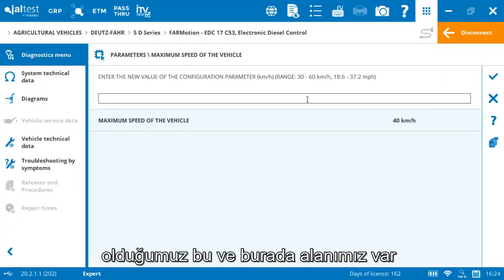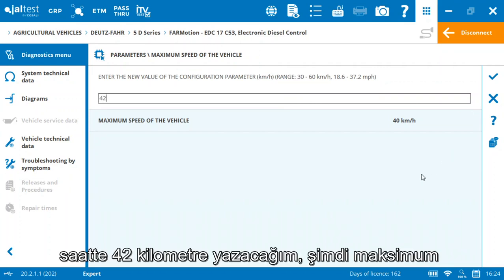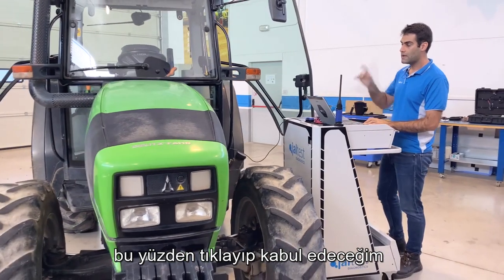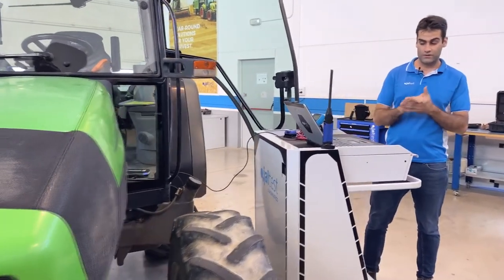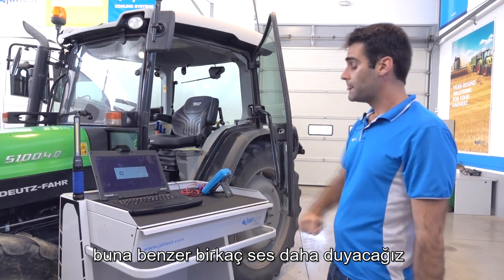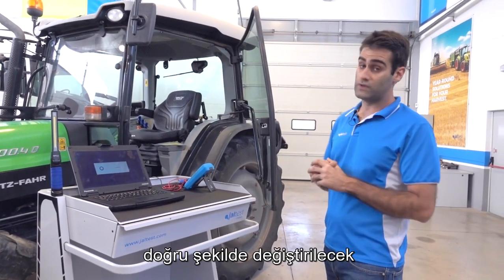And here we have the field, and that's where I can enter the maximum speed. I'm going to type 42 kilometers per hour. Now the maximum speed, as I told you, is 40. So I'm going to click and accept. Can you hear this noise? That means that we are modifying the parameter. If everything is correct, we are going to hear some more noises, like this one. And then the process is going to be finished and the parameter is going to be correctly changed.